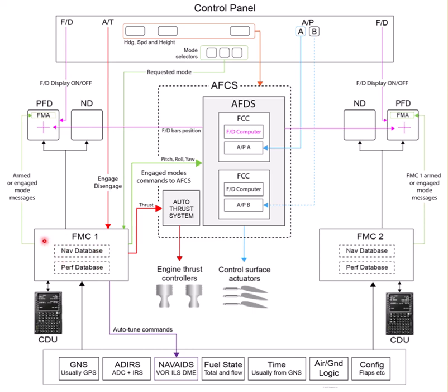Now you can of course put in a cost index, and that's one of the main things really, because when you put a low cost index in, the system does its best to save you fuel. This means it's going to take longer to get somewhere, but you will save money and you will save fuel. If, for instance, you were late off chocks, say an hour, and you've got a 6-hour flight, it's quite possible that you could catch up that time simply by putting in a high cost index and getting to your destination on time, which means you're not going to have passengers delayed, misconnecting flights, that sort of thing.